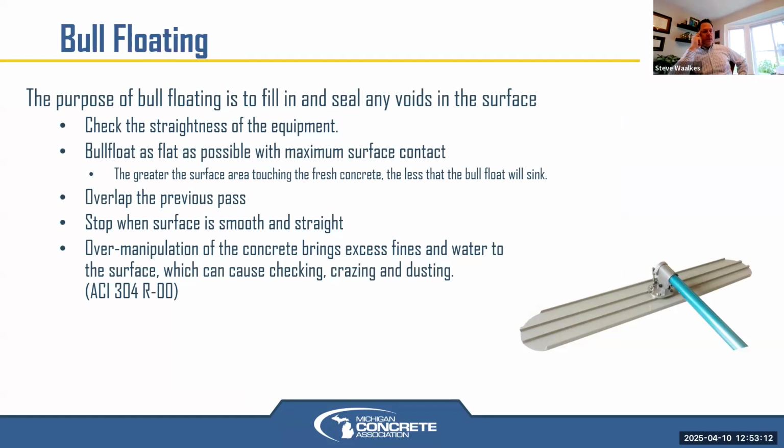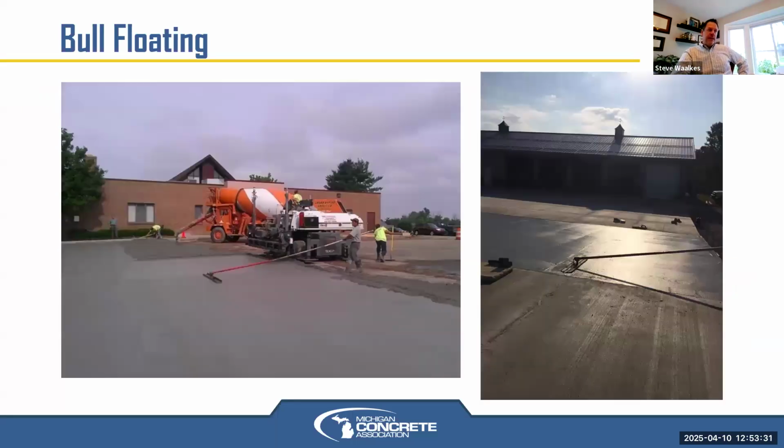You make sure your bull float is straight and is in good condition. Typically, you do it flat as possible with maximum contact. You don't have it on an edge as you're pushing it across. Overlap, stop, and don't over float anything, which brings excess fines and water to the surface, which can negatively impact your surface. So it doesn't have to have the rounded edges.